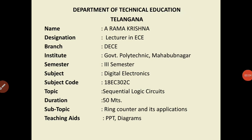In the previous lecture, we started discussing the different types of counters, that is synchronous counters and asynchronous counters. In addition to that, we have also seen the differences between synchronous and asynchronous counters, and the working of an example of an asynchronous counter, that is the ripple counter, a 4-bit ripple counter, which counts the number of clock pulses up to a maximum of 16, 2 to the power of 4. Since it is a 4-bit ripple counter, it can count up to a maximum of 16 clock pulses, 0 to 15.